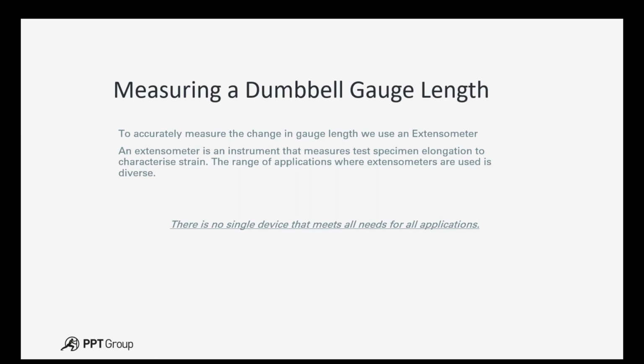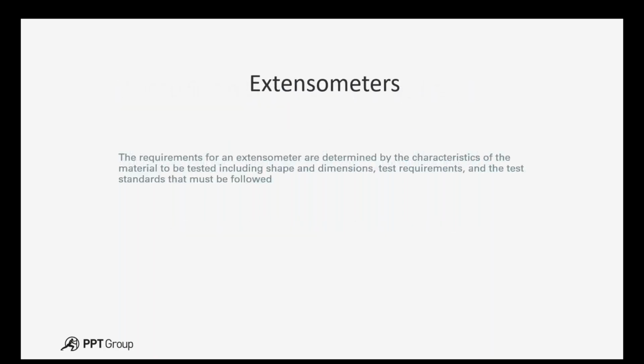And the range of applications where extensometers are used is very diverse. And you tend to find there's no real single device that meets all the needs for all the applications. So the requirements for an extensometer are determined by the characteristics of the materials to be tested, its shape, its dimensions, the requirements of the test, and a test standard if you're following one.